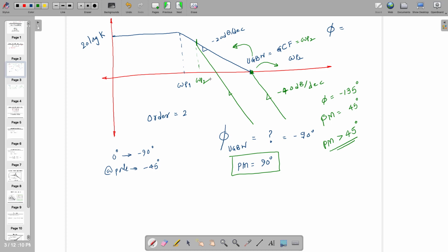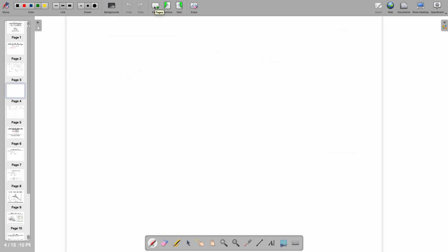Phase margin is 0 degree, so you will have some ringing, right? So you cannot avoid it. All these systems are unstable. If the system is just first order, it's the best system which you can have, but you cannot avoid extra poles and zeros. Just for your understanding.